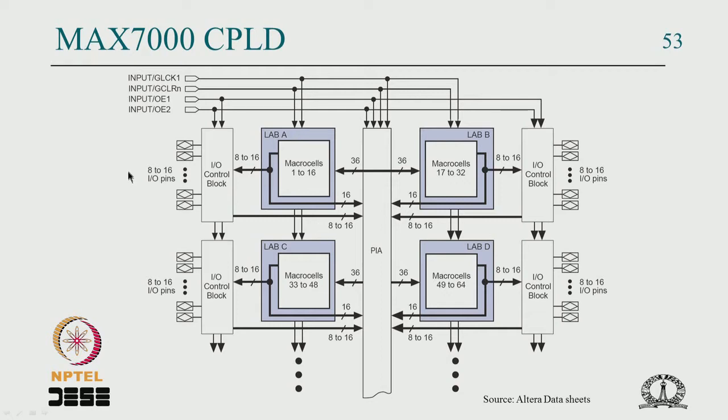And why it is called a crossbar is that the inputs come like a horizontal row and the outputs go as a vertical row, and at the intersection you can assume a switch, so all possible connections are possible. That is why it's called crossbar, which essentially comes from the old telephony nomenclature.